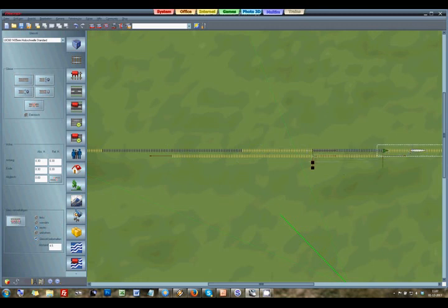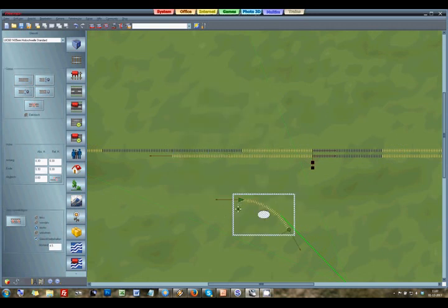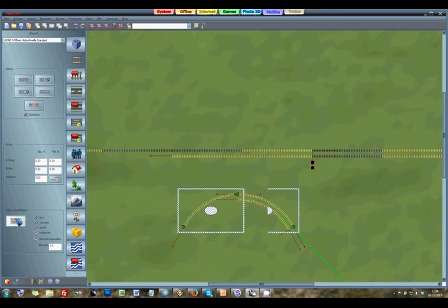And 1 more, and then we are going to make a little curve down. That is on the angle and radius mode. That is a negative angle of 60, and let's take for the inner loop a radius of minus 50. Also the radius you have to give a negative value, which is quite strange, but it is no other. I need an outer loop too for that one. And then I also need a forward copy, but backward, a mirrored one. We need that later.